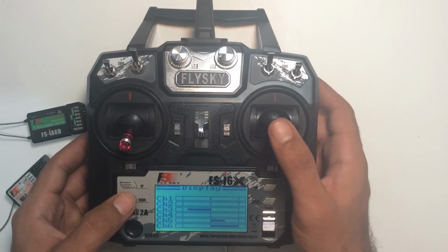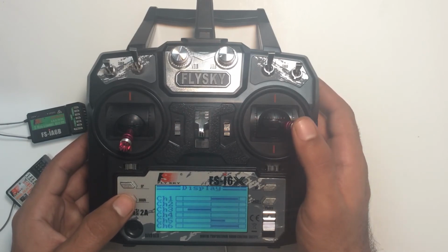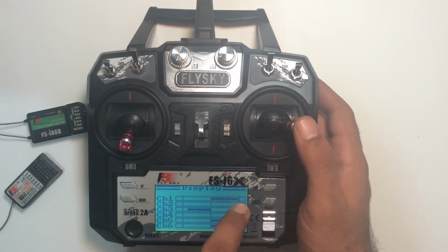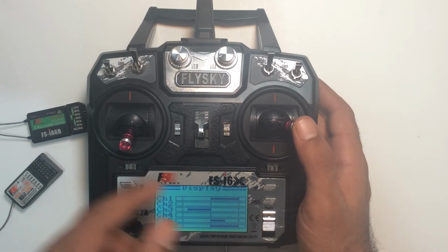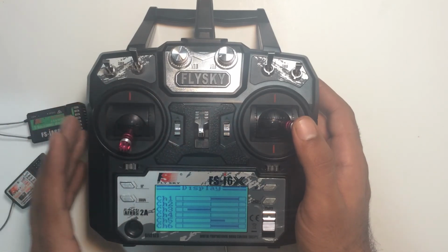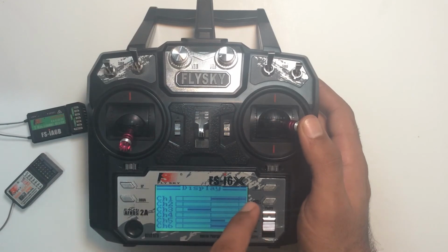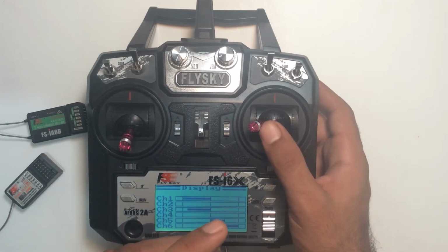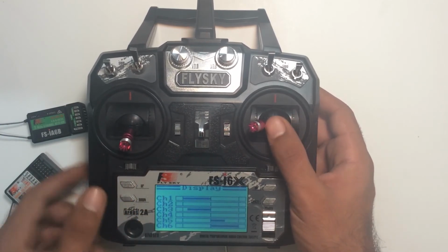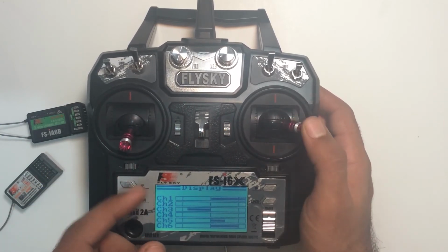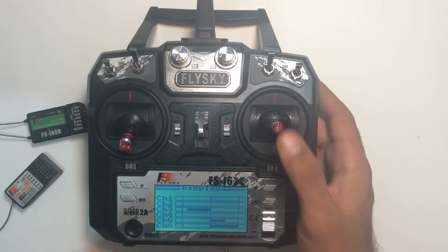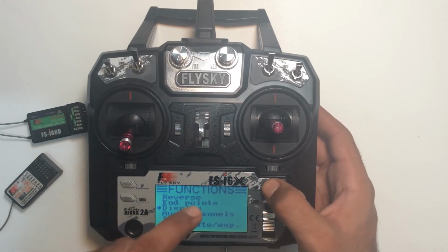So in the display, upon full movement of your stick, it moves up till this line. But when I set the limit to 120, then upon the full stick it goes to here, up till the end. So on this side it was 100, so it will move up till this line, and the side which was moved to 120 moves up till the extreme position. So that is actually the endpoint.